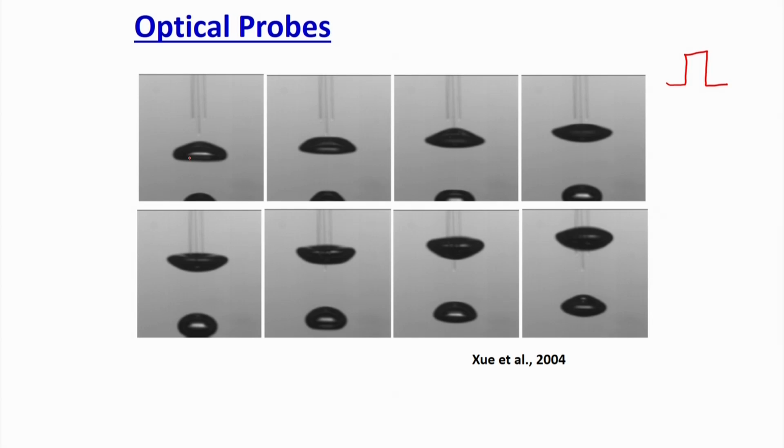Now, that is the major advantage, but it also comes with a disadvantage. Once the bubble passes through, ideally speaking, I should see an on-off system, like a TTL pulse. Now, what does that mean? Once the bubble is approaching the needle, and there is no bubble at the needle right now, your voltage should be in the range of the voltage of the pure species.